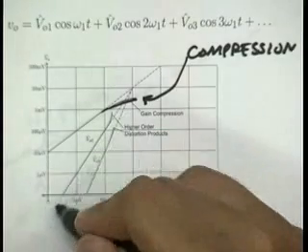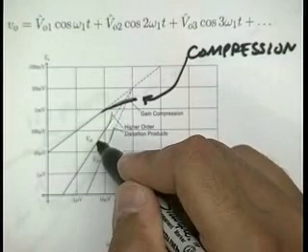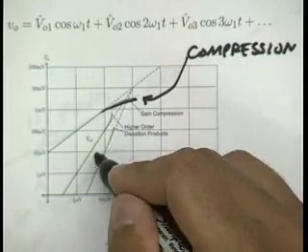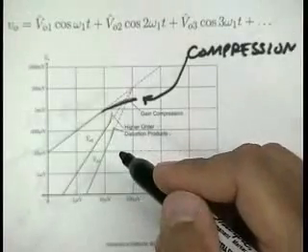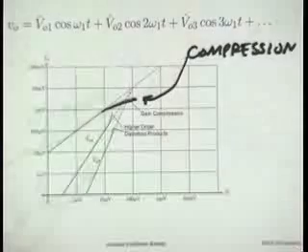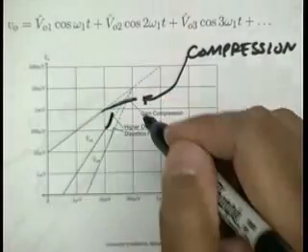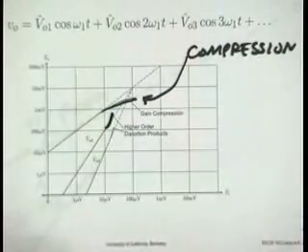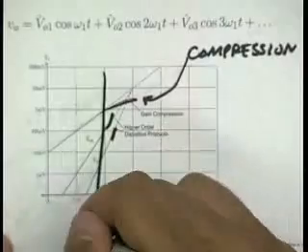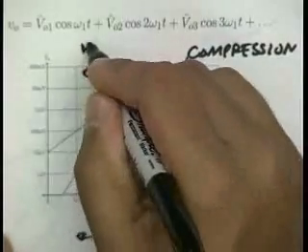You can see the second order follows this 2 to 1 curve. That's when the second power is dominating the second harmonic. But when the fourth order term comes in, right, the slope should change to 4 to 1. The sixth order comes in, the slope should change to 6 to 1. So we see the slope going way up here. Likewise for the cubic term. So the region where we say this system is weakly nonlinear is to the left here.